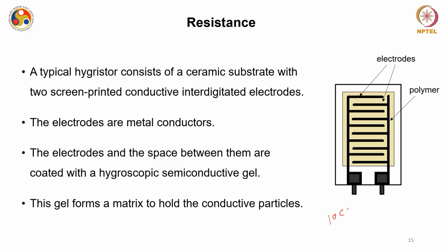If you go into technicalities, gold cannot be deposited directly on these substrates because of adhesion issues. So usually you deposit a very thin layer of chromium, say 10 nanometer of chrome, and on top of this 90 or 100 nanometer of gold. Similarly, platinum electrodes are very difficult to sustain on silicon substrates, particularly on Si/SiO2.